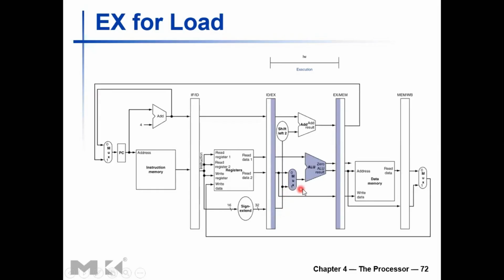So that will need to go through this multiplexer, and the multiplexer will consume a little bit of time, right? A small amount of time after the reading of the pipeline register. The multiplexer will consume a small amount of time to update the new values at that set of wires there, that 32-bit line there. So the control signal to be sent to the multiplexer should have also been saved in the pipeline register by the control logic, generated from the previous clock cycle. That should also connect here. We are not showing the control signals for the sake of simplicity yet.